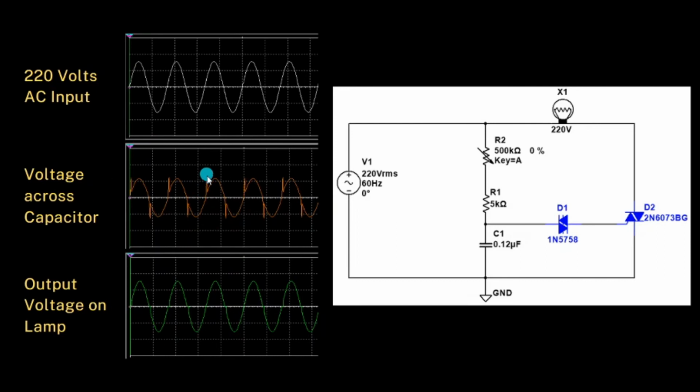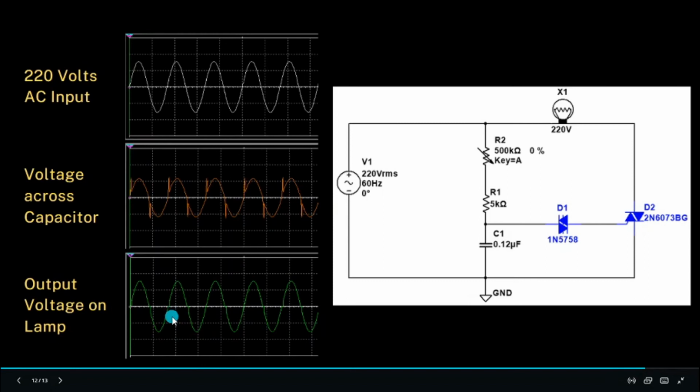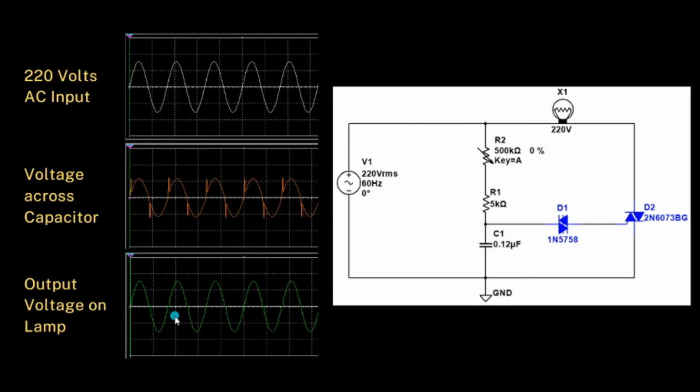And actually, this spike in voltage, that's the time, okay, if we look, it's leveled here. So there is actually some portion on this one that is zero, okay, and then our DIAC breaks over, and only then is there an output voltage. So you will notice, class, that our input, okay, if this is the input, here a small part is cut off. Okay, a small part is cut off when only the 5 kilo ohm resistor is present on the circuit.